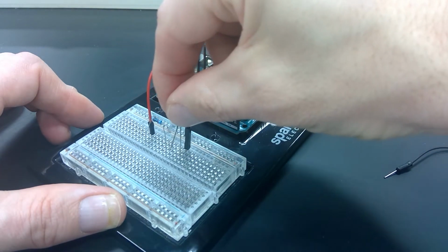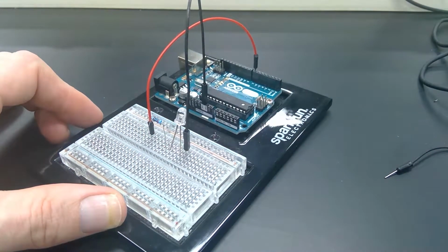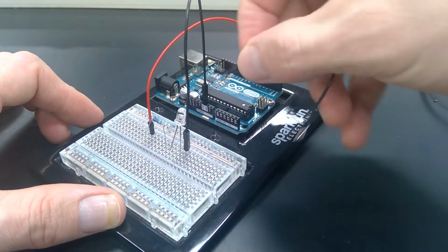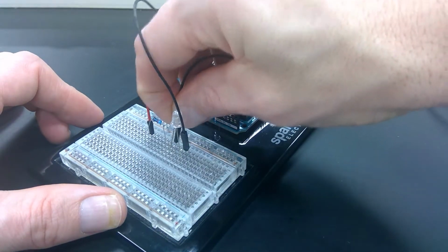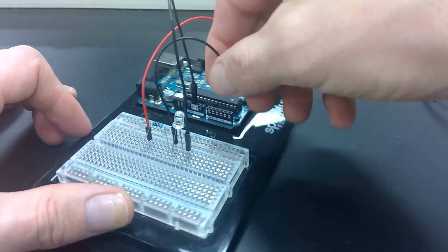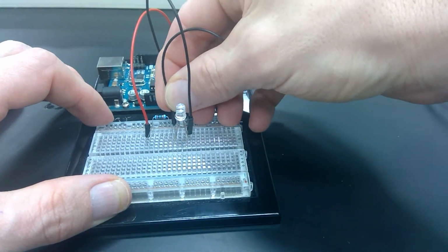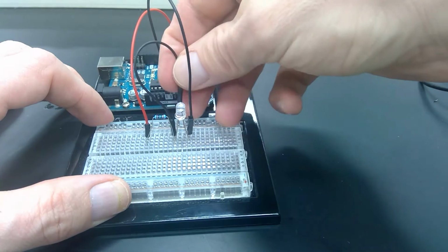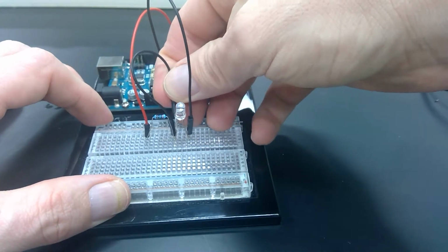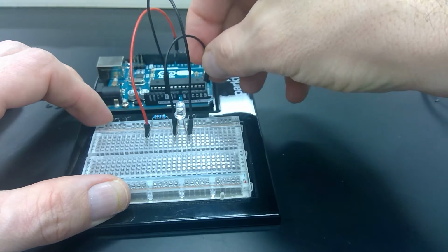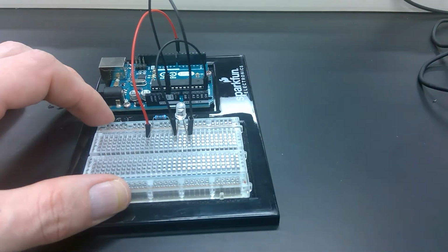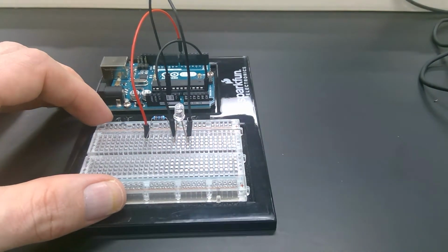Go. Put the wire behind the LED. Makes it easier to see. All right, so then the only thing I want to do is monitor the voltage right here between the resistor and the LED. So I'll plug that wire into the same row where the resistor and the LED are connected, and then that'll go over here to analog pin 5. That's it. That's the circuit. All right, we're ready to go.